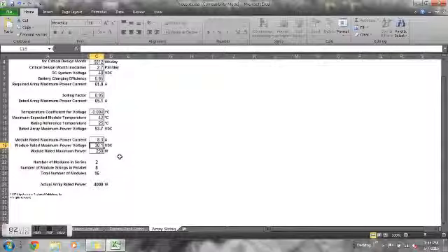To meet the array requirements, we would have to put 2 modules in series, and then we'd have to have 8 strings of those series modules to get the current necessary. This is a total of 16 modules in our array, and the rated power would be 4 kilowatts.